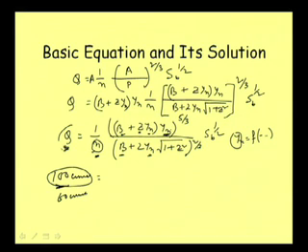So, you put a second trial value for normal depth which is higher than this one, and with the higher value of yn you calculate again. Suppose you get 90. Then you calculate a third value, and suppose you get 110. That means this time, in the third trial, the value of yn you have put is more than what it should be.